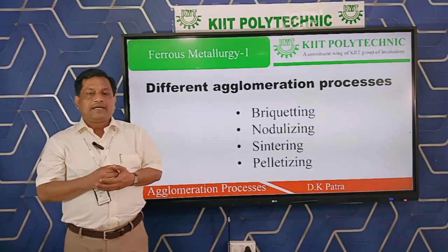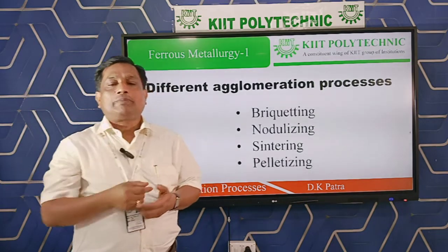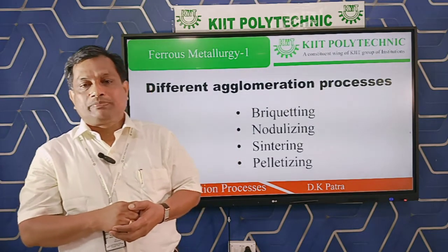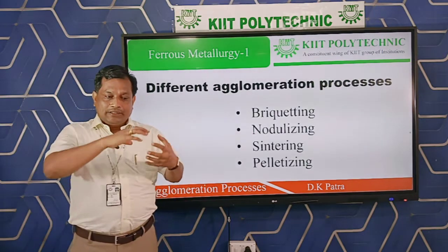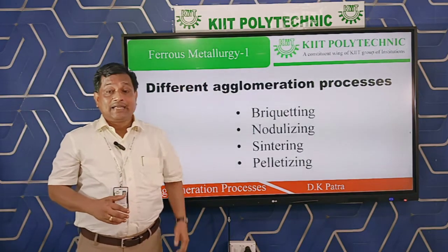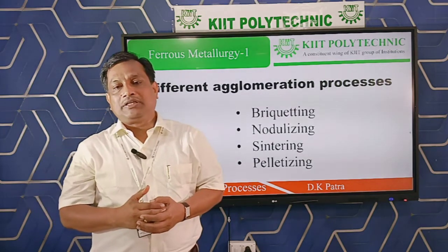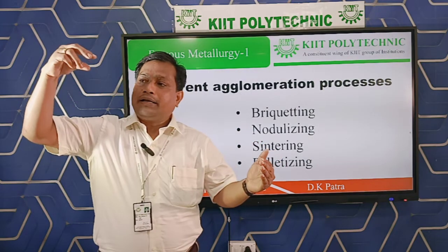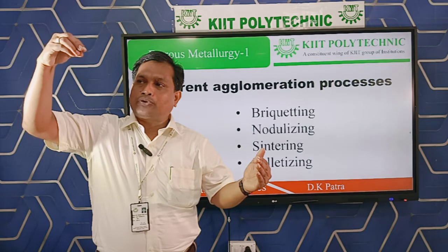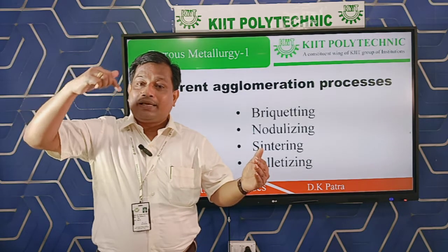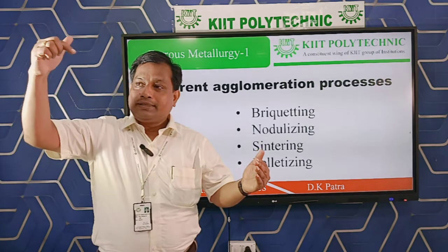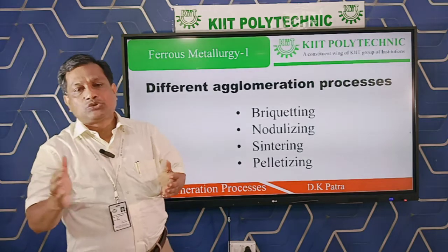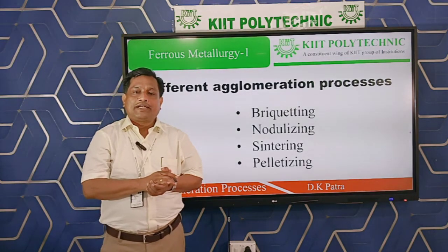Here it is a little different. Again we take small particles of iron, that means iron ore is crushed, then it is mixed with a carbonaceous material like tar. The mixture is put in a rotary kiln, which is around 30 to 60 meters long. We put the material at the top of the inclined kiln, which is rotating at half rpm, and the material comes down. It takes around 2 hours to cover the entire length of the rotary kiln.